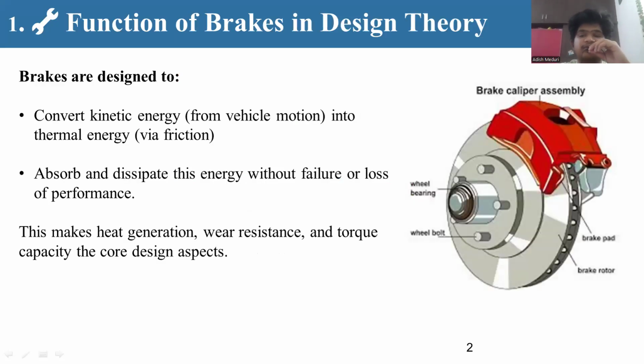First, to understand brake fails, we need to understand functions of brakes in design theory. Brakes are designed to convert kinetic energy from vehicle motion into thermal energy via friction, absorb and dissipate this energy without failure or loss of performance. This makes heat generation, wear resistance, and torque capacity the core design aspects.